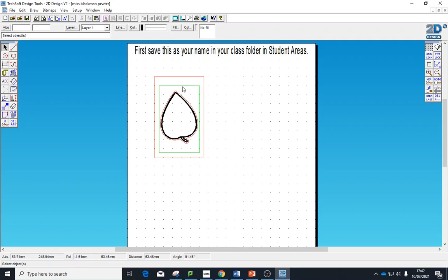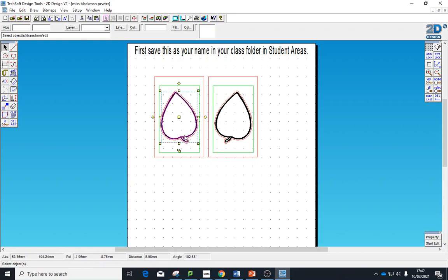So in that case, I've just pressed undo. I'm going to select all of this, use the copy box at the bottom, and then the flip here. And I'm just going to move those so that they are side by side. So what I'm going to do here, on this side, so this side will be my blank. I'm going to have that like that now. So it will just cut out that shape. And then I'm going to delete the opposite line on the other piece. So what will then happen is these will be sandwiched together and the molten pewter will be poured in and it will cast the detail that I have engraved on the surface here.